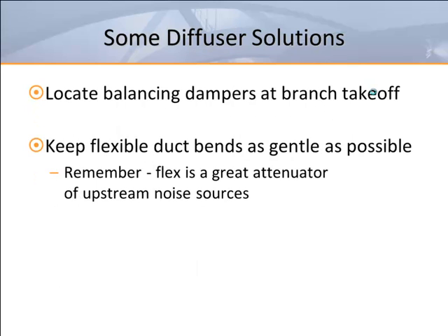Some recommendations to minimize noise. Locate balancing damper as far from the diffuser inlet as possible. Provide as much straight duct, emphasize straight, into the diffuser inlet as the space will allow. Acoustic flex at the inlet will help attenuate unwanted airborne noise.